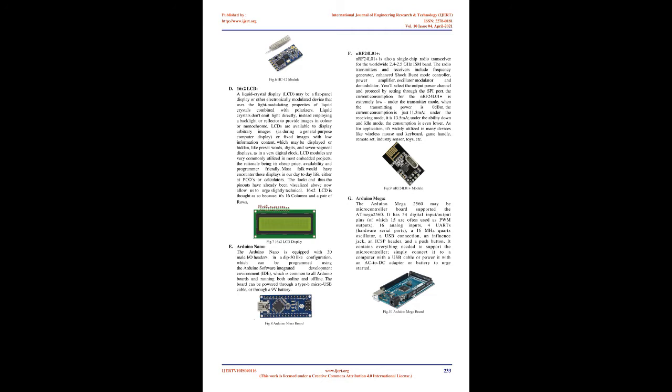B. NodeMCU. NodeMCU is an open-source firmware, and open-source prototyping board designs are available. The term NodeMCU, properly speaking, refers to the firmware instead of the associated development kits. Both the firmware and prototyping board designs are open source. The firmware uses the Lua scripting language. The firmware relies on the Lua project, and is built on the Espressif non-OS SDK for ESP8266. It uses many open-source projects, like LuaJSON and SPIFFS. Its support for the 32-bit ESP32 has also been implemented.